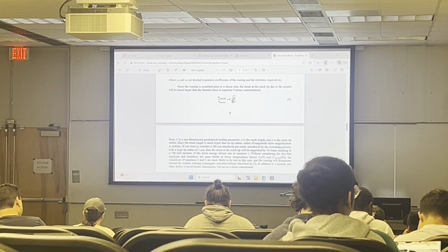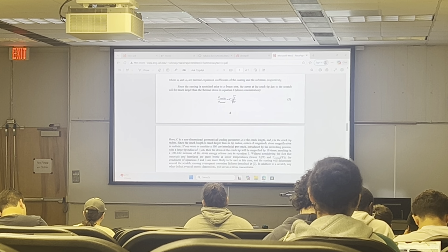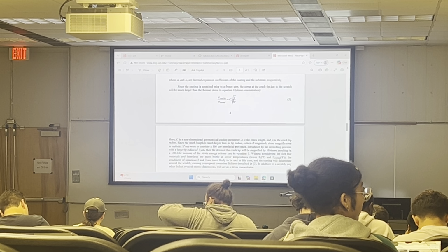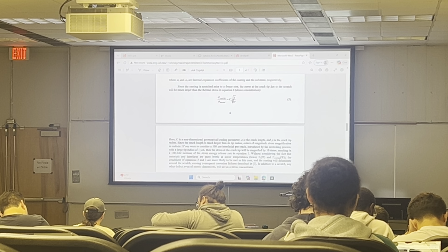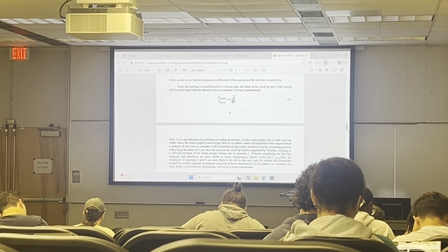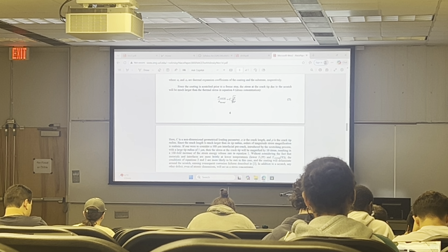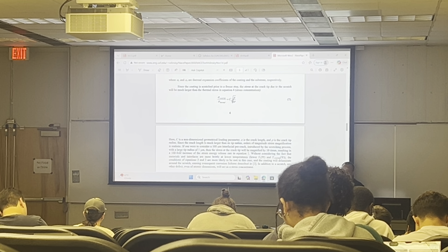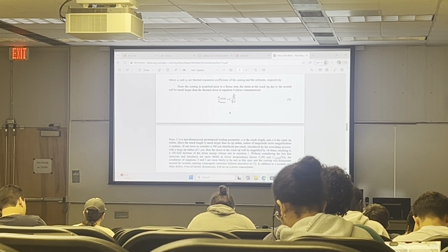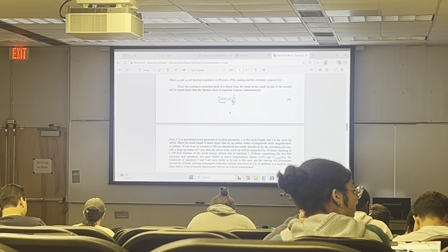Whenever you have a crack, in this case this is the tip radius, and this is the crack length. I can tear it up like this, and then all of a sudden it's much easier for me to continue this process. I can continue like this, it's very easy. But if there's no flaw, I can try to do that. See how much force it requires for me to do that? Much higher. So this stress concentration is determined by this equation. Typically the crack length is very long and the tip radius is small, so you have a large number divided by a small number.